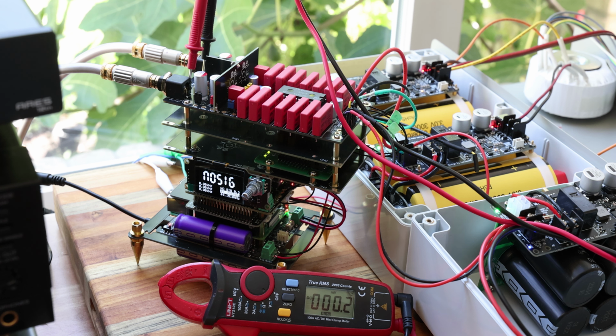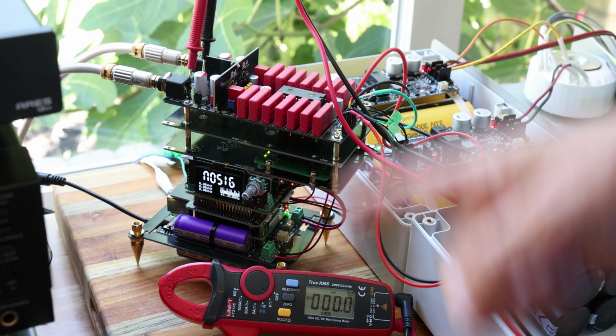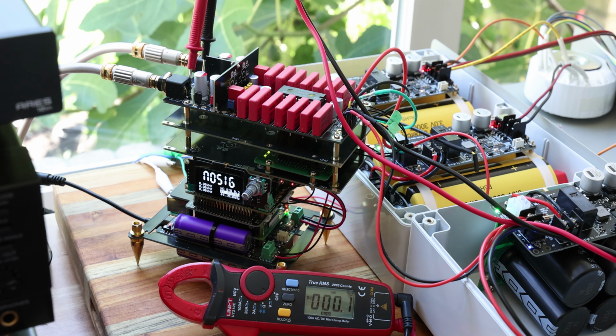Anyway, if you just have 100 millivolts, don't worry about it. Most amplifiers, like I said, can handle DC. It's no problem. I mean, it's not desirable, but it's not like it's going to kill your amplifier. As long as it's not above 2 or 3 volts, you should be okay. It's not going to kill it, because even when you have music, it fluctuates on plus and minus 2 volts. But we'd like to keep it as close to 0 as possible. So set it to 0, and if it fluctuates a little bit, don't worry about it too much.